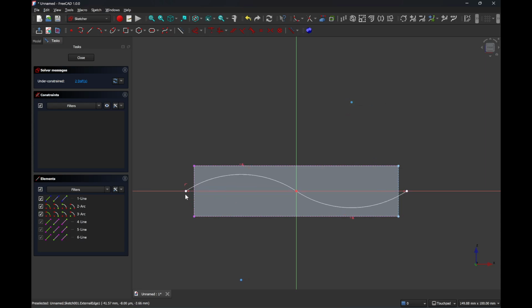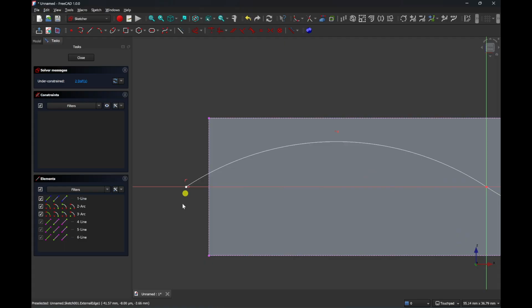But what we want to do, in an ideal world, is put this dot directly in line with the edge of that extrusion. But it turns out when we cut it later, it causes a problem just because of minor differences. When it's slicing, it can't slice the entire object. So because this is going to be the slicing geometry, we'll make that stand outside by about 0.1 of a millimeter.